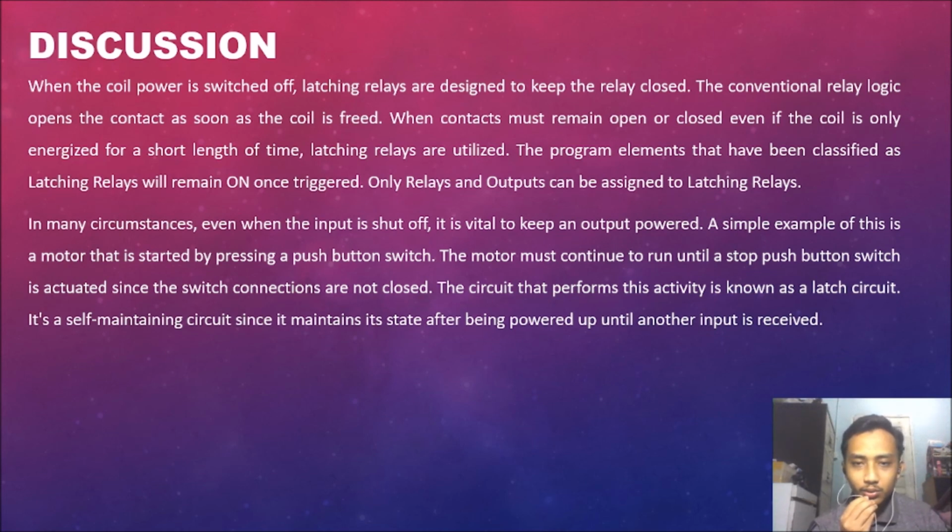The motor must continue to run until a stop push button switch is activated, since the switch connections are not closed. The circuit that performs this activity is known as a latch circuit. It's a self-maintaining circuit since it maintains its state after being powered up until another input is received.